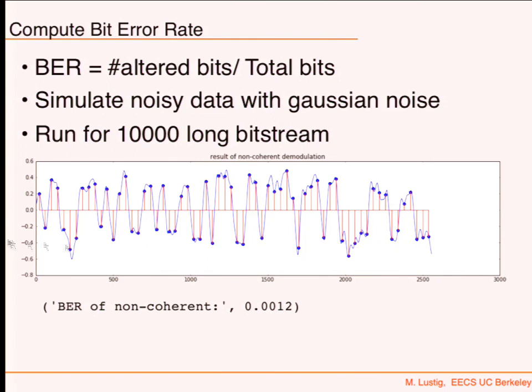And so this is 1, this is minus 1, 1, 1, minus 1, minus 1, minus 1, 1, 1, 1. And as long as this one, within the noise margin, doesn't switch to the other side, then you're good. You'll get a good recovery. And this is what's nice about digital communication. If it goes through, it's perfect. Okay? Up to a certain level of noise margin.